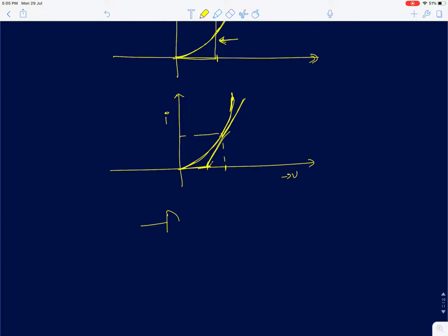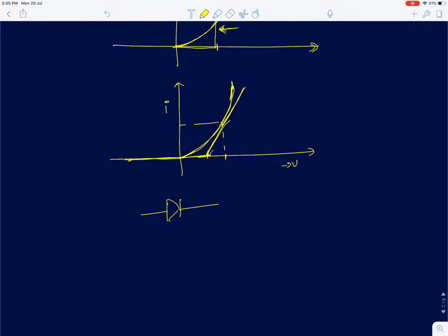So in this case, your diode in the forward bias region, since the reverse bias is always simple, you can simply assume it as an open circuit, it's done. All these models we are talking about are mostly in the forward bias direction. So in the forward bias direction you can model this as a zero cut-in voltage diode in series with a voltage source and a resistor. I am going to call it R on, the on resistance of the diode, and this V gamma. Now how do you find R on?